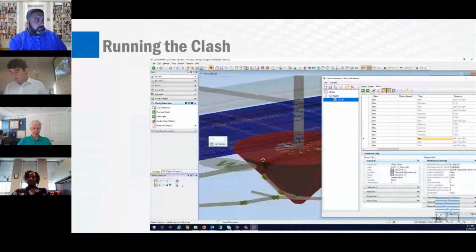So once the parameters for the two sets of data to clash are set, we're ready to begin the clash detection. On the right, there's a menu for performing the clash detection, and the result of the clash detection is now shown. Typically, depending on the size of a project, this takes perhaps a minute or two. The data is displayed as a table with the type of clash mentioned early in the center, as well as whether it is a hard or clearance clash.